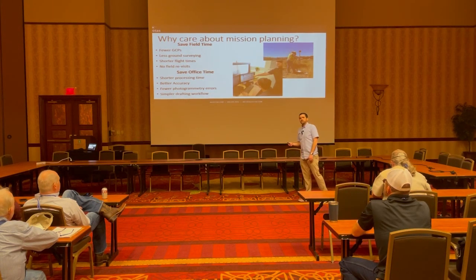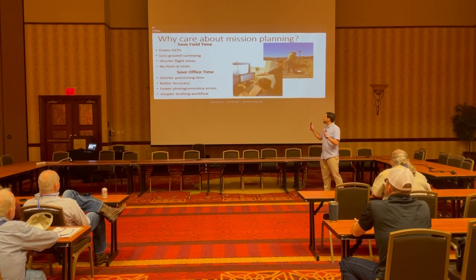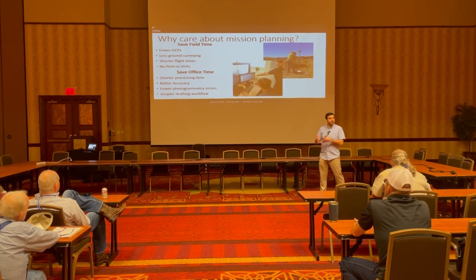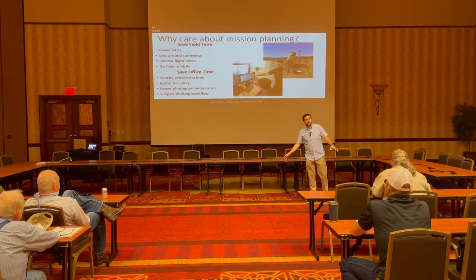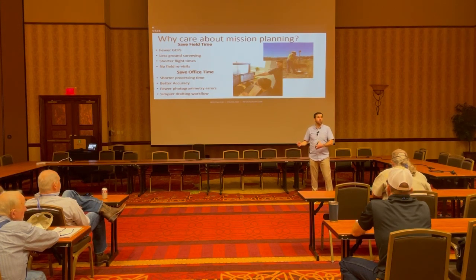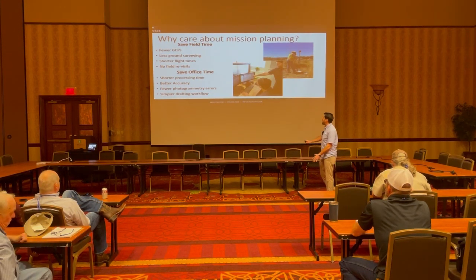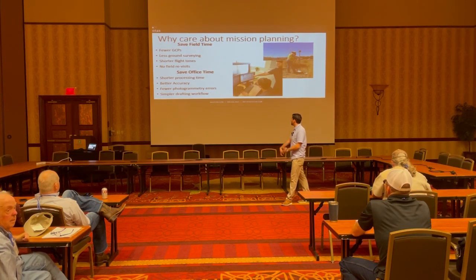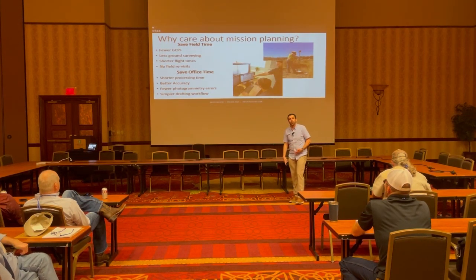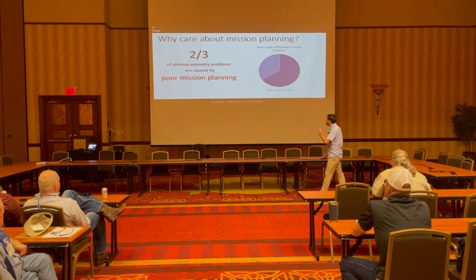But also, mission planning sneakily saves a lot of office time. If you collect the right data, then it gets processed faster. There is absolutely such a thing as too much data in this world, where just transferring it can take hours and processing it can take days. So it saves office time by having good mission planning. And it also leads to fewer photogrammetry errors and a simpler overall workflow.